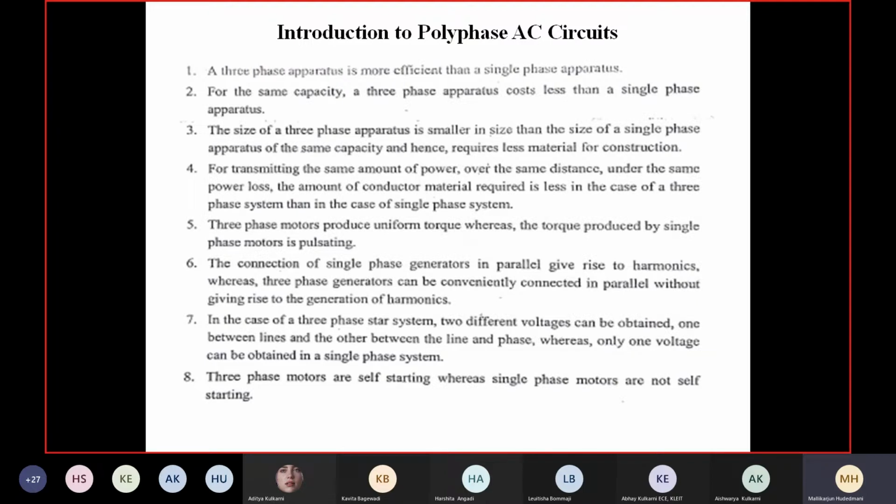Like that, a three phase AC system has a facility or provision to have line to line voltage and line to phase voltage. This is the advantage of three phase AC. So from the existing three phase AC, delivering power to the single phase loads is just draw a line and connect. This is not there in other single phase AC.